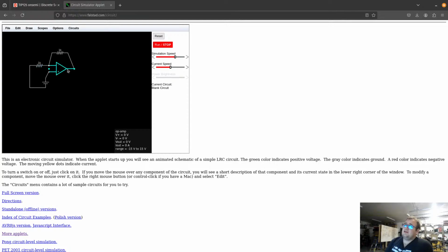And it will change the output to try and get us there. So the way it will change that output, in this case, oh wait, I wanted this to be 20K. Apply. Since it's applying it to the non-inverting input, that means it will try to raise this voltage up.